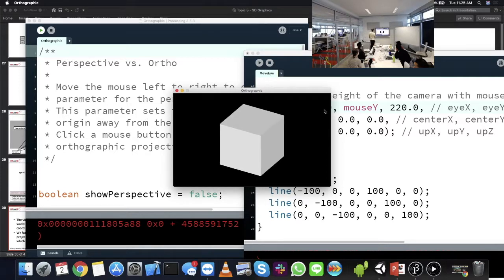What's key about orthographic is that it maintains parallelism, it maintains length and everything. So if we look at this example here, we know that this should be a cube, but those two lines definitely aren't parallel. Those two actually aren't too bad, but those lines there aren't parallel. So parallelism is lost. Length is lost, even though that should be a cube. The sides appear to be different lengths. What orthographic projection does is it maintains all these things.